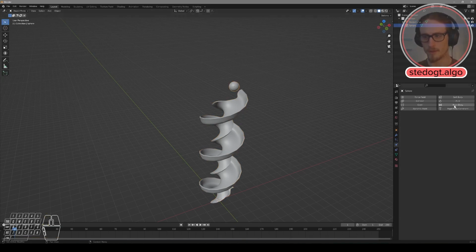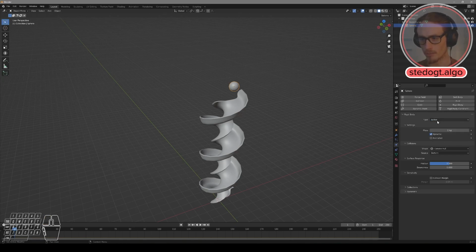Now for rigid body physics, on the UV sphere, this will be an active object. I might take it up to 2 kg. And the shape of this sphere, I want this object to roll down the surface, so I'll set the maximum friction and maybe slight bouncy.